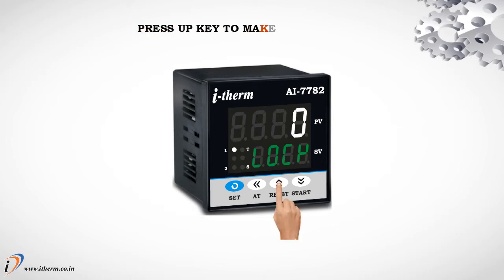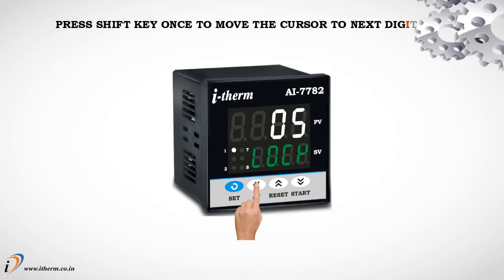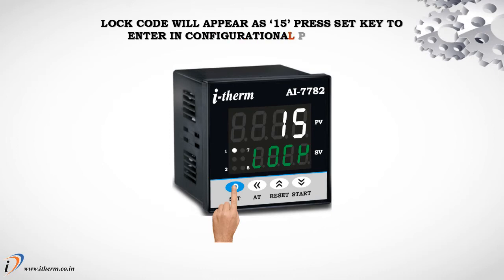Press the Up key to make the unit digit 5. Press the Shift key once to move the cursor to the next digit. Press the Up key to make the unit digit 1. The lock code will appear as 15. Press the Set key to enter the configurational parameters.